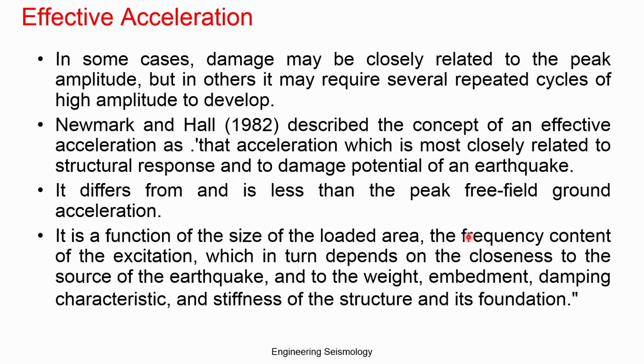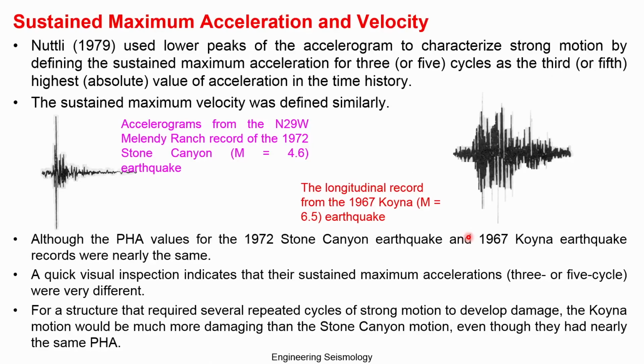So, this is the acceleration which is most closely related to the structural response and the structural potential of the earthquake. It differs from, and is less than, the peak free field ground acceleration, as a function of the size of the loaded area and the frequency content of the excitation, which in turn depends upon the closeness of the source of the earthquake, embedment, damping characteristics, and stiffness of the structure and its foundation.